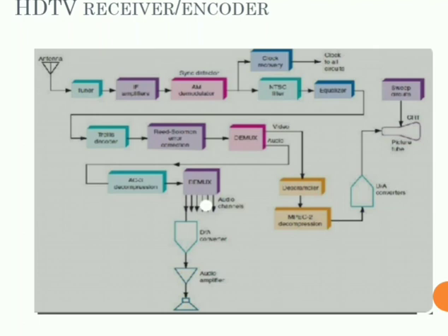A balanced modulator is used after that. The balanced modulator is used along with a carrier signal that is phase locked to the pilot carrier, to ensure that accurate demodulation is being done. There is also a clock recovery circuit that regenerates the clock signal that times all the remaining digital operations. The purpose of the clock recovery circuit is generating the clock signals.